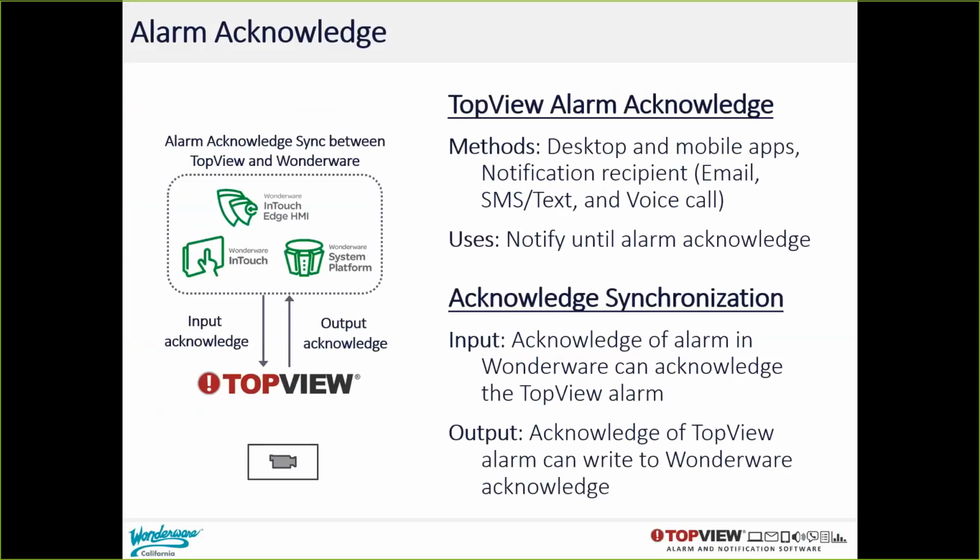TopView allows you to synchronize the alarm acknowledged state in TopView with the Wonderware alarm acknowledged state, so that an alarm acknowledged by the operator on the HMI can acknowledge the same alarm in TopView, and an acknowledgement of an alarm in TopView can acknowledge the alarm in Wonderware. So let's look at a demo of alarm acknowledged synchronization.